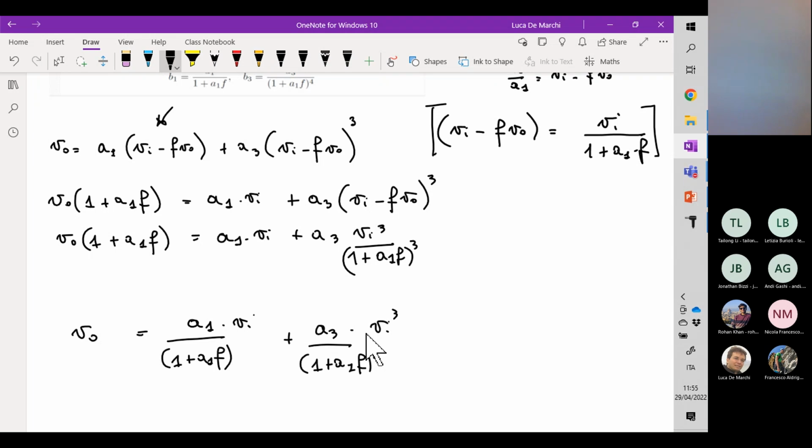Okay, so let's suppose that our amplifier is characterized by this single order transfer function. This is in the Laplace domain, so you must imagine that this S can be converted into J omega. So basically, this is a single pole transfer function.